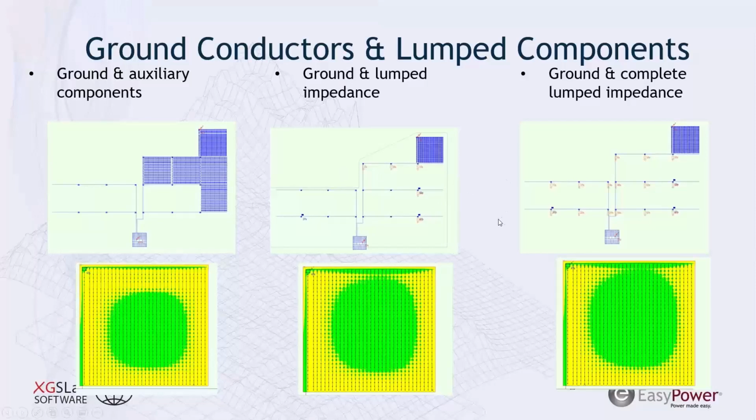A fun thing that you see for these very large systems, if I look at a system that's a lumped impedance just around my regions where I'm focused versus lumped impedances throughout my system, I didn't make a huge improvement on my system performance comparing these two. And that's an indication that for this particular model on this particular system, what's happening out in this environment isn't going to play a large role in a fault that occurs in one component of your system.